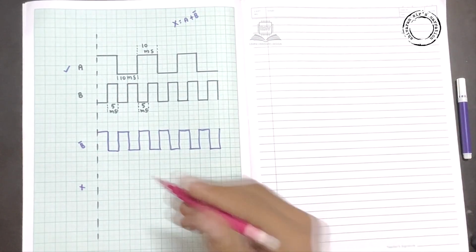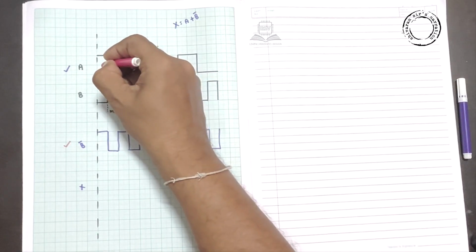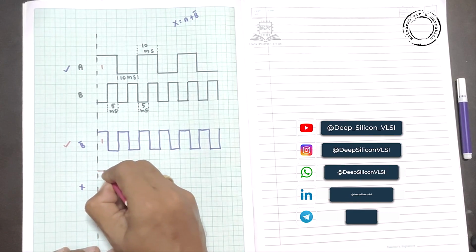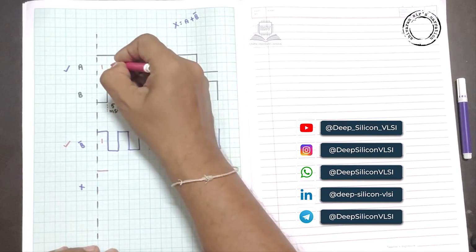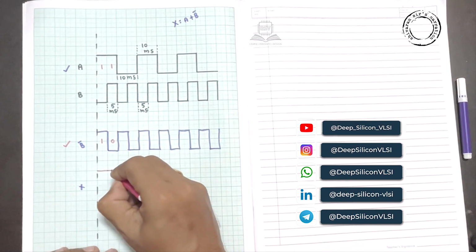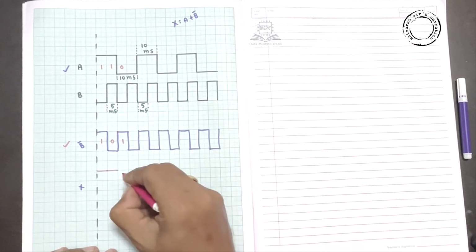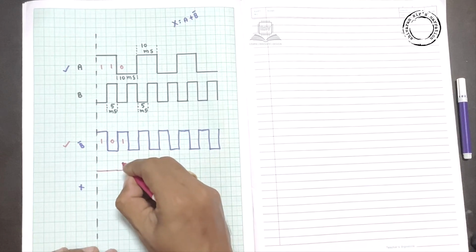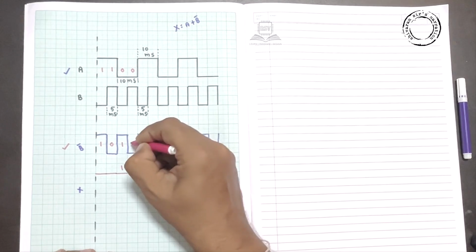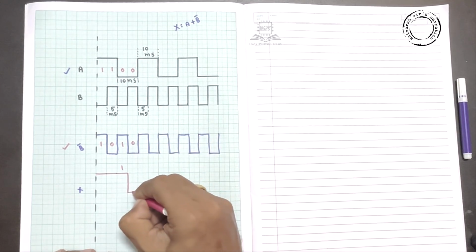Now here the inputs are B bar and A. So in this case it is 1, 1. Hence output will be 1 only. Again 1, 0: 1 plus 0, 1 only. Similarly 0, 1: 1 only. Again here 0, 0, then output becomes 0.